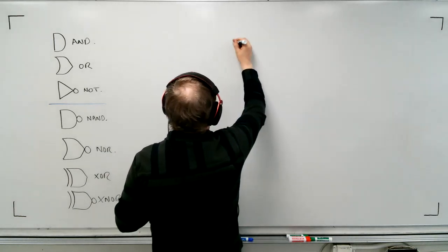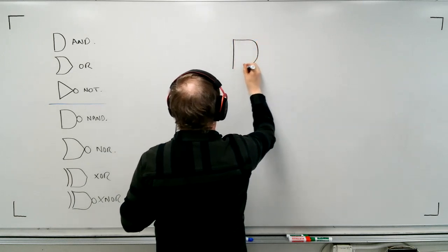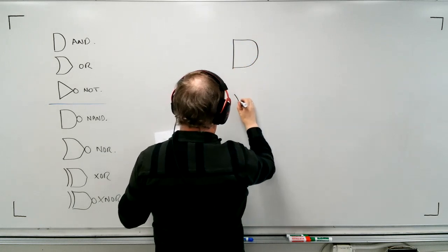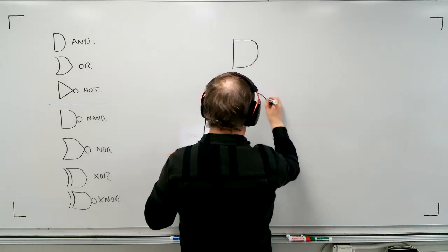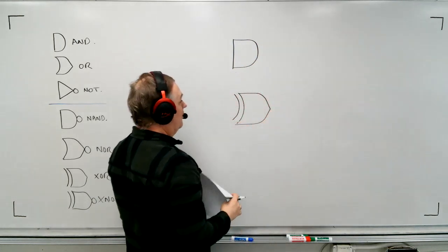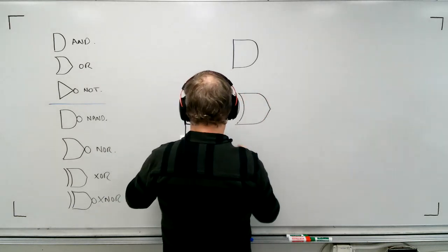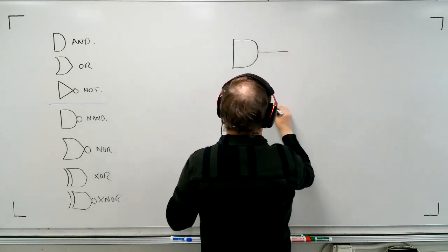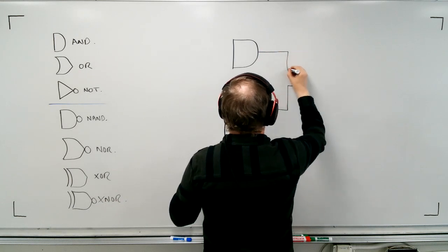I'm going to put in an AND gate right here. And I'm going to also put in just down here an exclusive OR. Now, an exclusive OR means it has to be a 1 and a 0 or a 0 and a 1 to give me a high output. Now, the output of this and the output of this XOR are going to come like this.